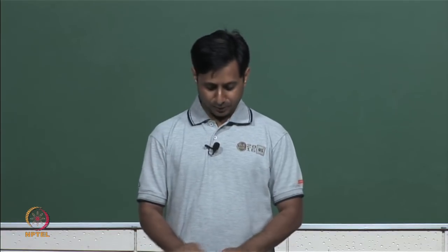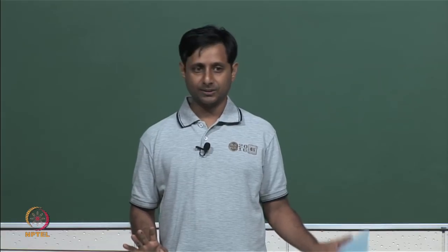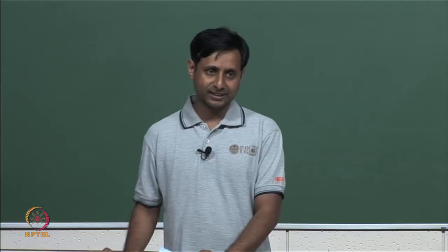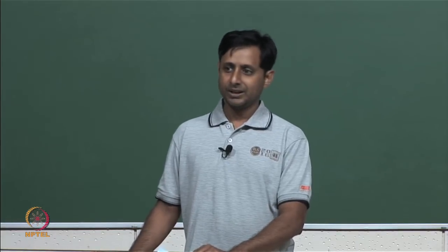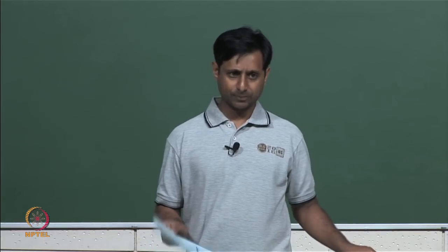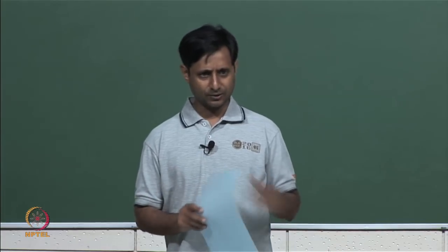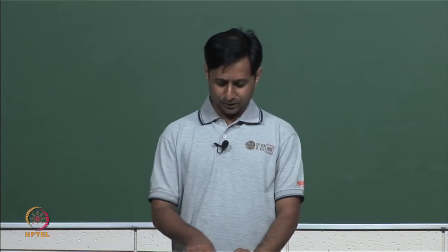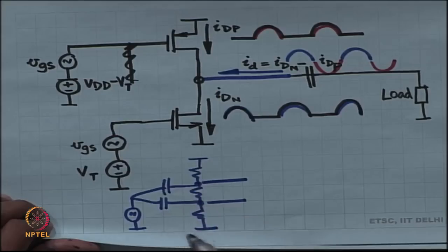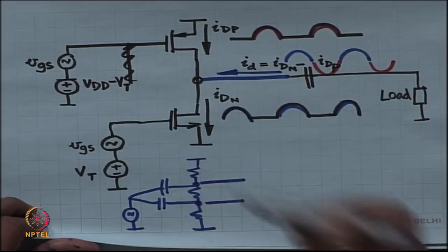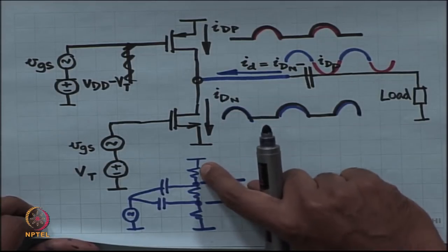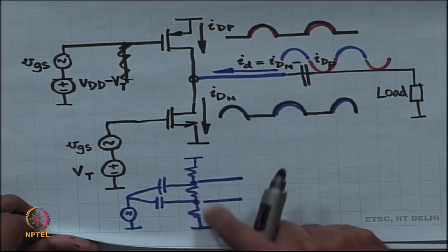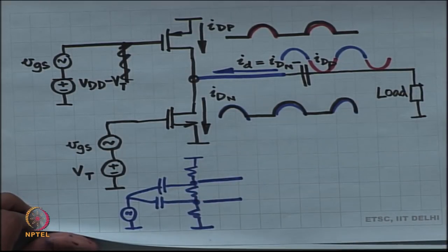Okay. With MOSFETs, you just have to organize these bias voltages right. With BJTs also, the problem is the same, organizing those bias voltages. They do a lot of tricks to do that with BJTs, they use diodes and so on. In case of the MOSFETs, you can use similar tricks. You can imagine a resistive network like this, where this drop just has to be VT of the PMOS, this drop has to be perfectly VT of the NMOS.